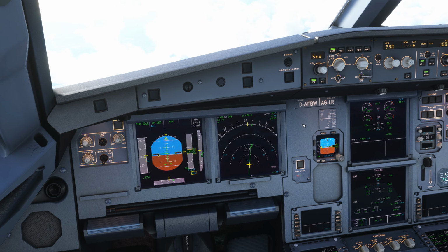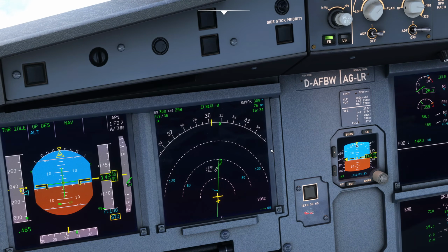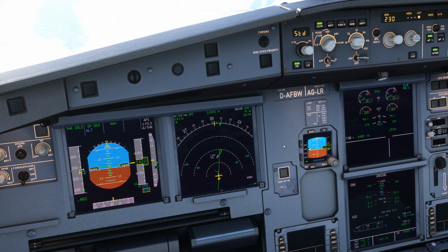It's very loud, huge amount of drag. So it makes a lot of noise at these speeds. At the lower speeds, it's not so bad, but there we go. So we're now below the landing gear extension speed of 250 knots, and we're below Mach decimal 67, 280 knots, of course. So let's give it a go.